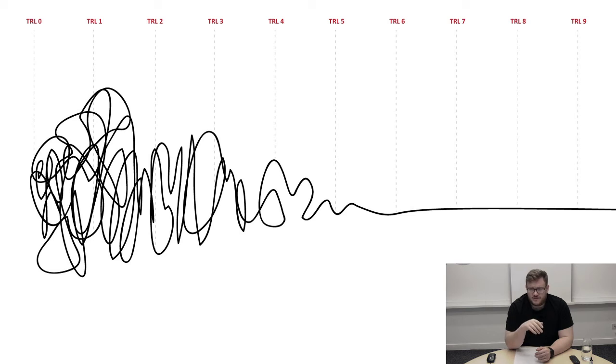And then carrying it forward, when you get to TRL 7, when you've got a pre-production prototype, that's kind of considered things like draft angles, assembly process. It's been really refined by that point, and to get to that point, it takes a little bit longer. It could take another 6 months or so. When you get to TRL 8, you've got things like tooling times. You've got freeing up of the machines for injection molding, if it was injection molding. And then if you have any tweaks to make, so you get samples back from manufacturers and they're not quite right, then you tweak them, and you do another sample, and you tweak them, and you do another sample.